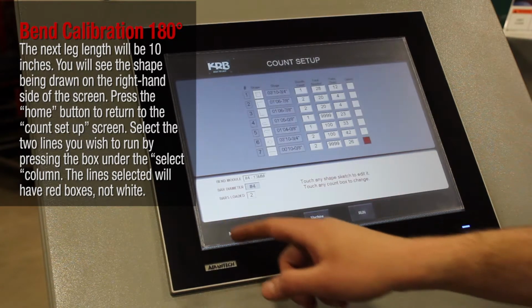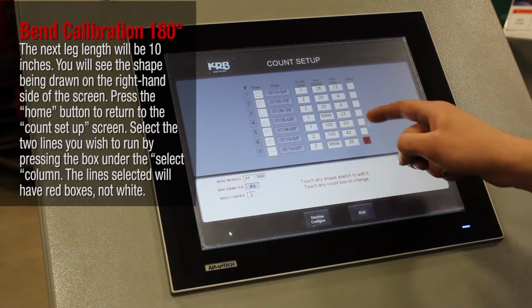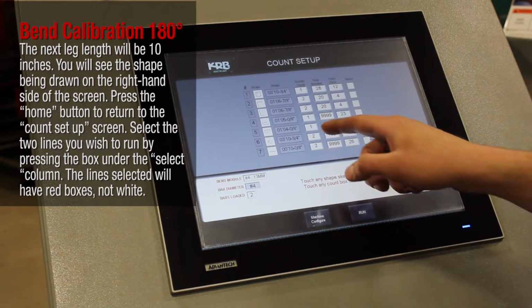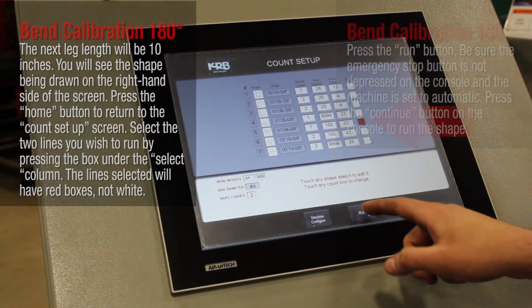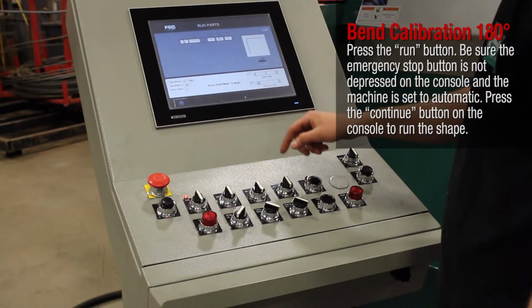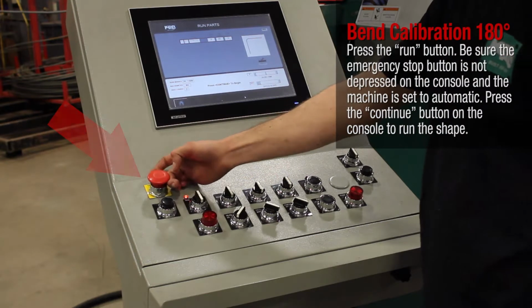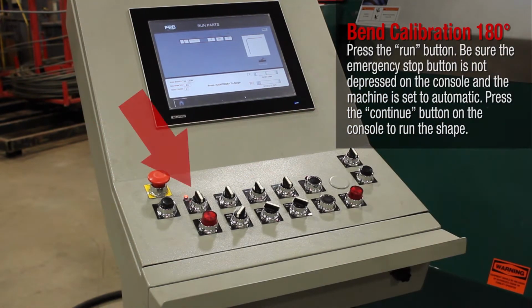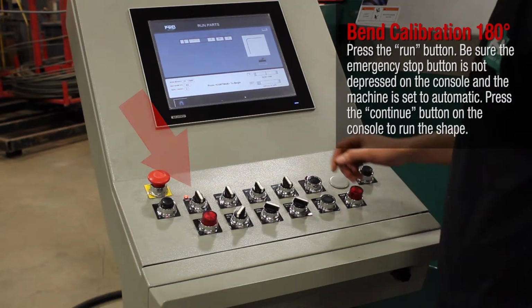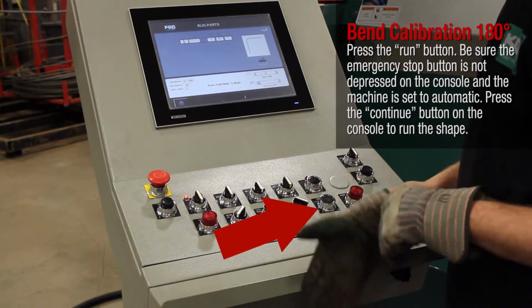Select the 2 lines you wish to run by pressing the box under the Select column. The lines selected will have red boxes, not white. Press the Run button. Be sure the emergency stop button is not depressed on the console and the machine is set to automatic. Press the Continue button on the console to run the shape.